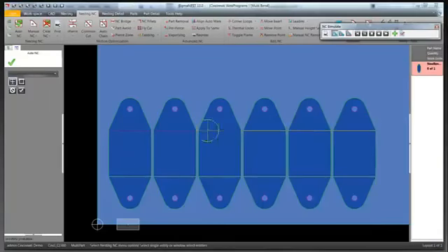So the first thing that we're doing, we have the option in SigmaNEST is to mark all the parts. These could define where the bend actually happens. Will help align things up with the backstop. So then we're going to come around the first part, and you're going to see we're going to jump over the top of all of these parts in order to accomplish this.